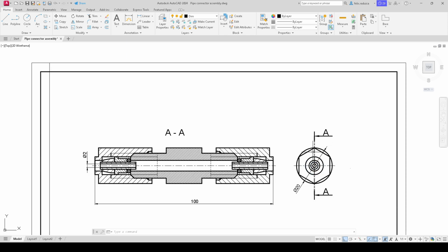And it doesn't need to be dimensioned all over, just the surfaces that might come into contact with an outer assembly that will assemble with this one, because most of the dimensions are already given in the dimensions of each part's detailed drawing.